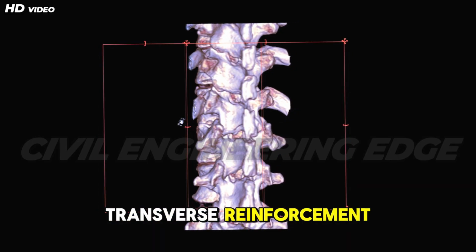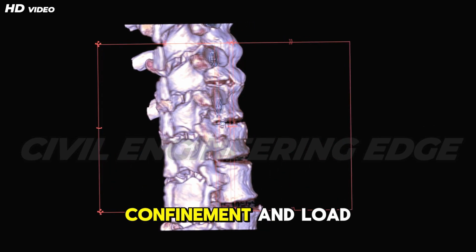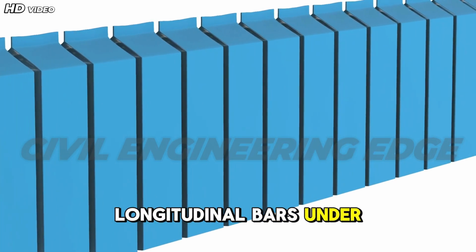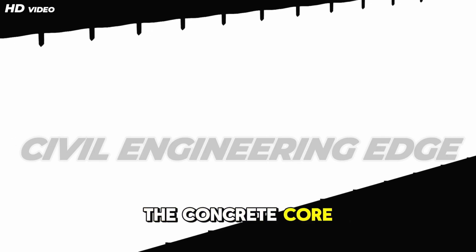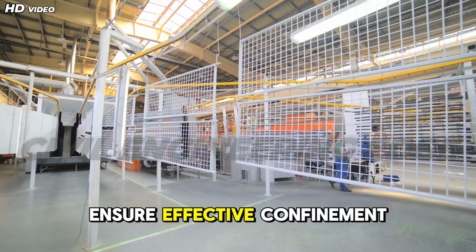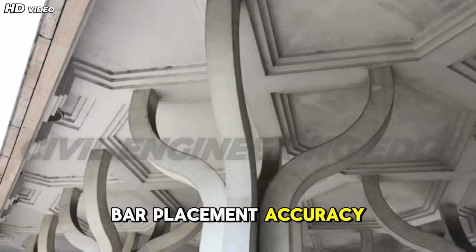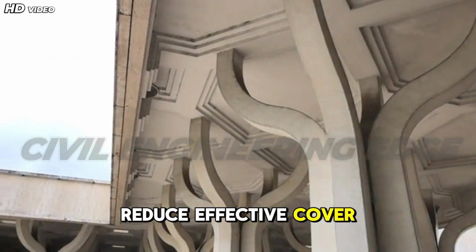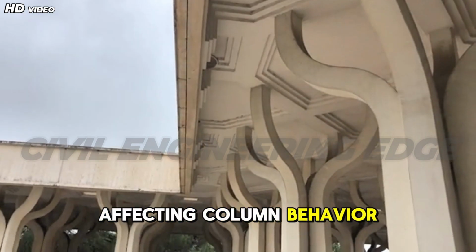Transverse reinforcement, such as lateral ties or spirals, plays a crucial role in confinement and load transfer. Ties prevent buckling of longitudinal bars under compression and improve ductility by confining the concrete core. Proper spacing and secure fastening of ties ensure effective confinement, especially in seismic regions. Bar placement accuracy is also critical. Misaligned bars reduce effective cover and can introduce unintended eccentricity, affecting column behavior.